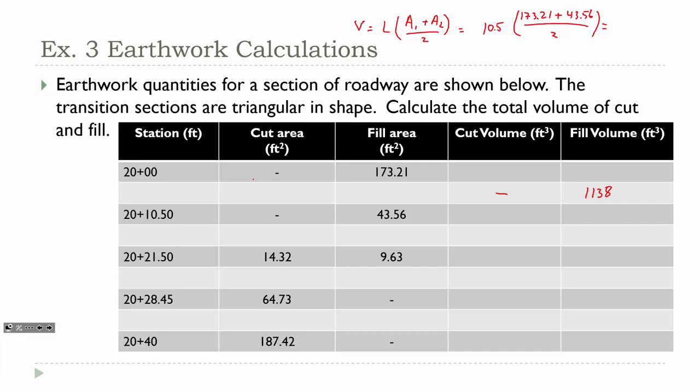Let's fill out the fill volume all the way down before we deal with the cut. Between the next two, let me write the calculation here. Our distance is 11 feet, and then we have 43.56 plus 9.63 divided by 2. 293.